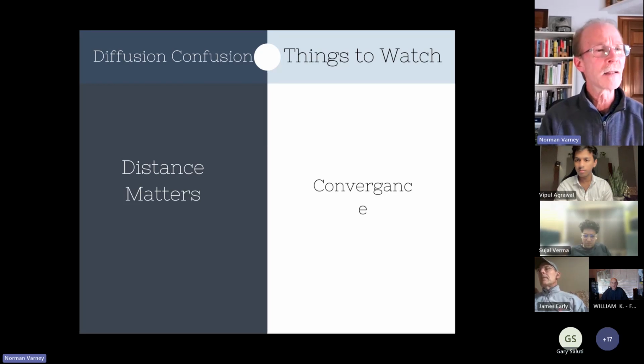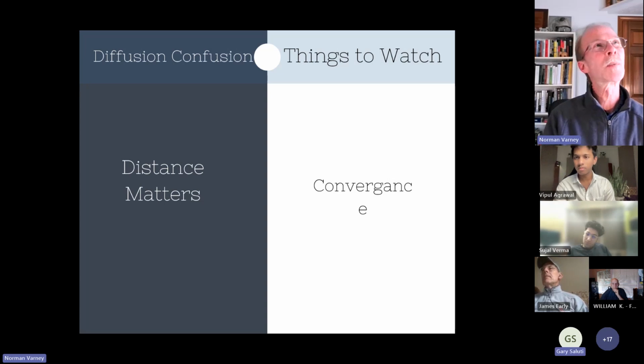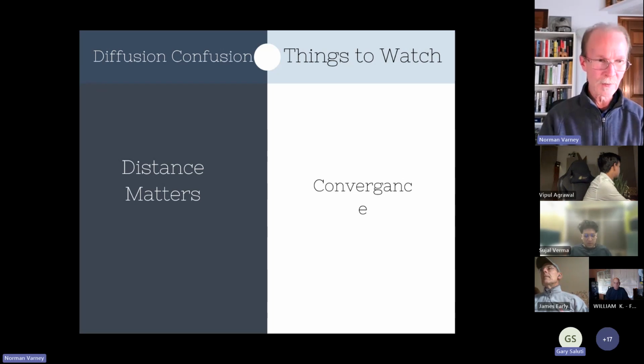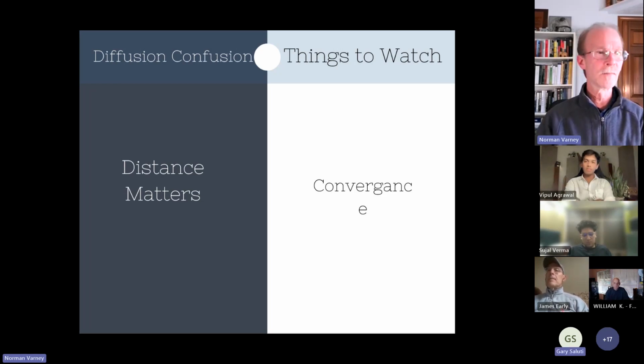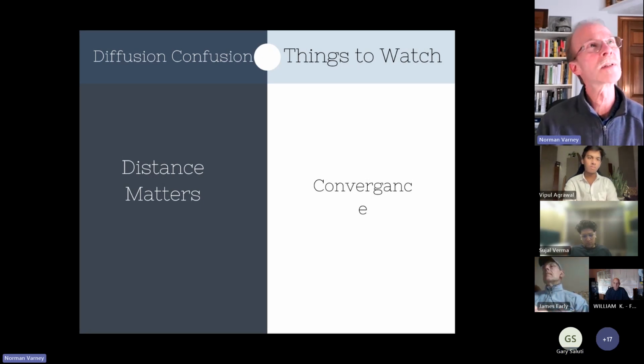And then after that, like I alluded to earlier, and I might be wrong about this, but I haven't experienced having too much after the reverberation times are under control and the first order reflection points, of course, are taken care of. Can you introduce too many diffusers? I mean, of course, you could end up covering up absorption that you need, but beyond that, I don't know that you could. Again, as long as you've got the reverberation times under control.